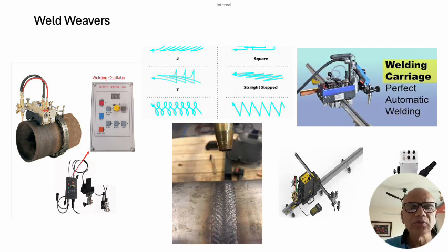And you need to have, as I said, a minimum of 2 or 3 parameters to be controlled. One is the motion you want, so your controller should be capable of designing this kind of path for your torch through one of these means which are used as weld weavers, or nowadays on the robots you can plan it on the robot itself for the weaving attachments, or the robot itself will weave.